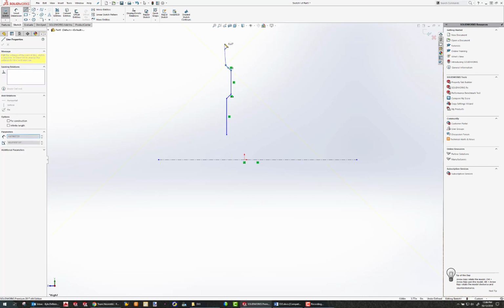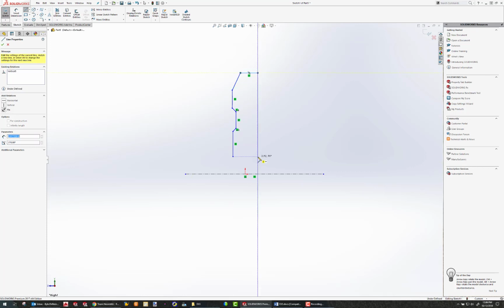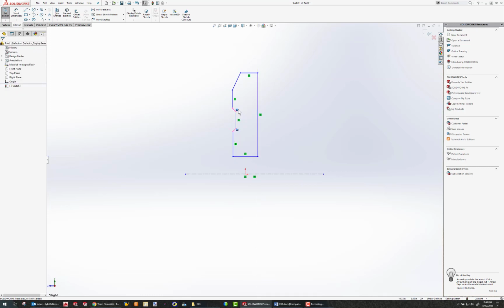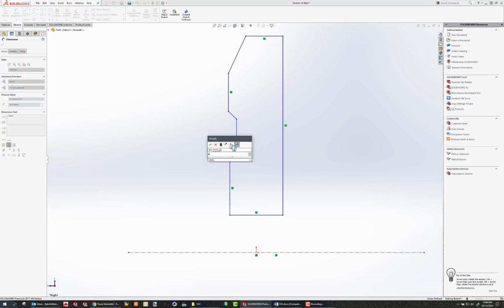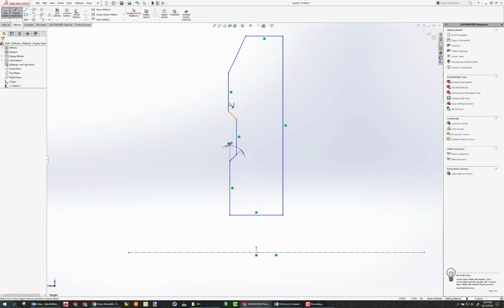And something that I want you to notice that just happened, and I did not mean for it to happen, is that this geometric constraint came in as this perpendicular. So it turns out that these lines actually are perpendicular because in the definition it's a 45-degree angle here and a 45-degree angle there. So the perpendicularity callout would be okay, but I don't want to actually add that because I want to manually type it in because that's how it's listed on my problem statement.